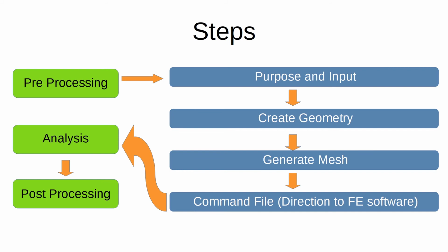The next step is to combine all of the inputs and the mesh generated into what forms the part of the analysis. We need to define the type of analysis. We need to define the material properties. We need to define what the displacements are, if any, or if the displacements are fixed in a particular direction. We need to define loads and boundary conditions. We need to also define if there are any load combinations. All of this can be done in efficient software. It can be done using a text editor or in the study module of Salome Meca.